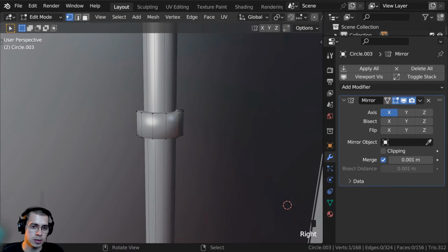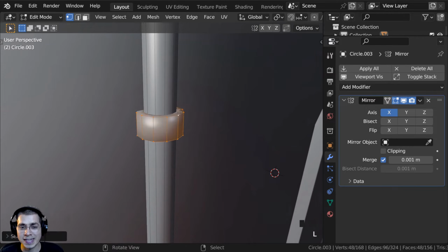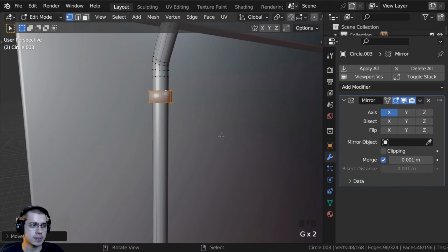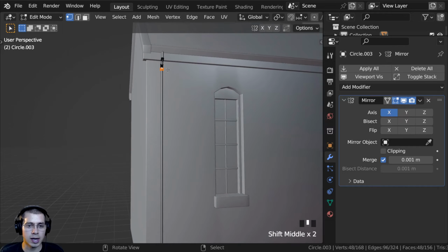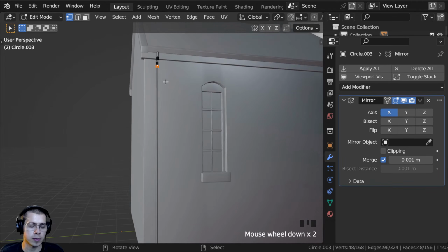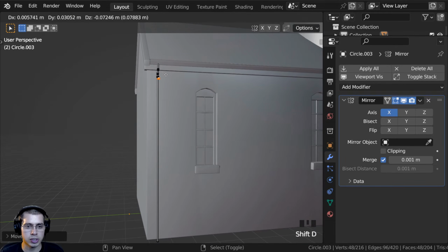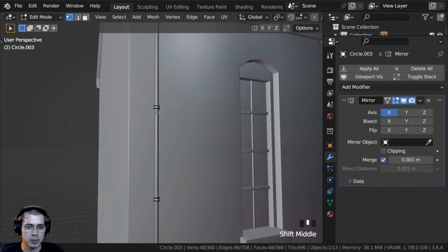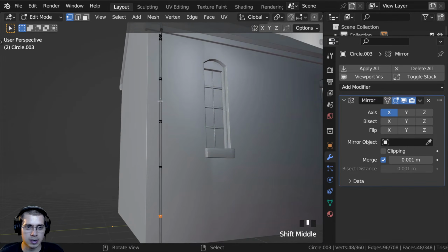And then back in edit mode, I'm just going to select this vertex here, and I'll press the L key to select all of the linked vertices. And I will bring this up on the z-axis till it's a bit higher. And then I want to zoom out here, and I want to make more of them, probably about 4 of them. So what I can actually do is just press Shift D to duplicate, bring it down on the z-axis, and place it about there. And because we did that all in one action, we pressed Shift D, then Z, and then bring it down and place it there, we did all of that in one action, so I can now press Shift R. So Shift R is going to repeat the last action, and I'm going to do that a few more times until we have those other pieces there to support the gutter.